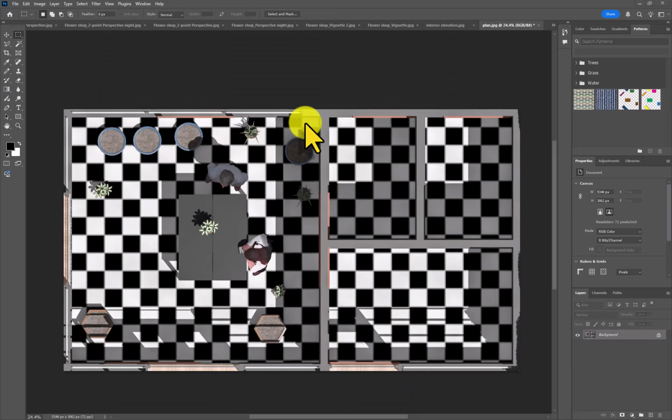One thing that you can do really easily in Photoshop is fix the poché, which never seems to work exactly right in Lumion. And to do that, we basically need to select all of the gray area. Now, in my case, I don't actually have that great of an export here. So I could try something like this magic wand tool. The way that works is you can click on a color, and based on whatever settings you have, in this case I'll choose contiguous and see if I can get all of the gray.